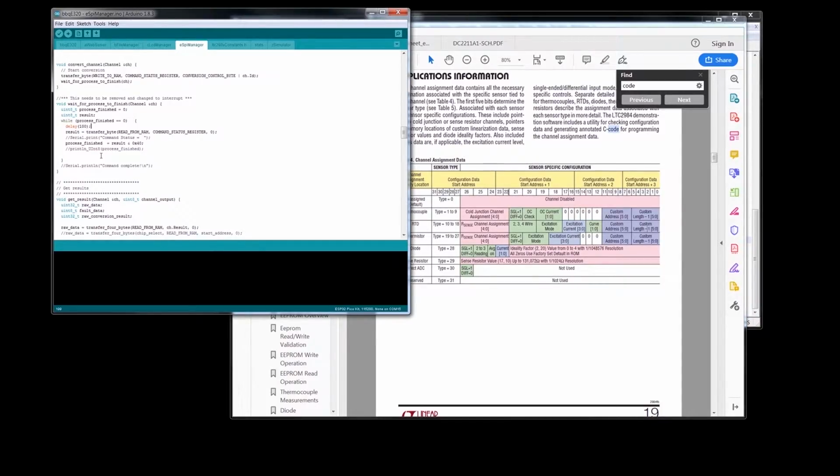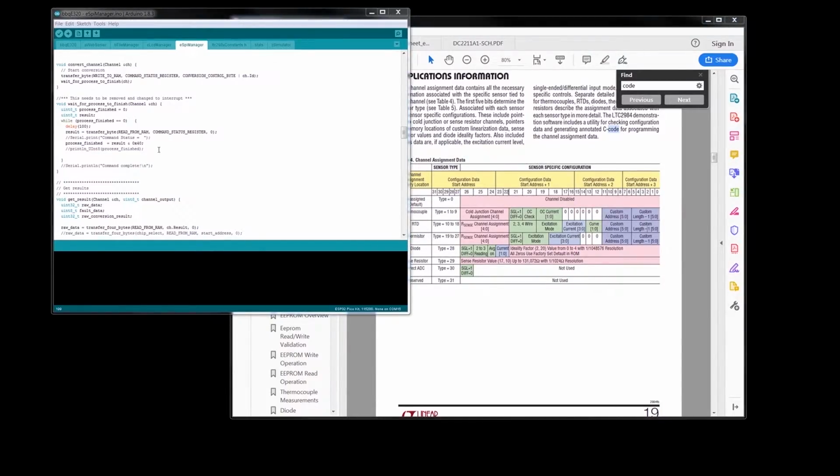So when the interrupt pin goes high, we'll know that it's done with the conversion process, and we won't have to sit here and just pound the SPI waiting for this command status register to give us this result right here, which I forget what this is, 100 or something like that. Anyway, that'll be a lot cleaner than putting these delays in. I really don't want that.